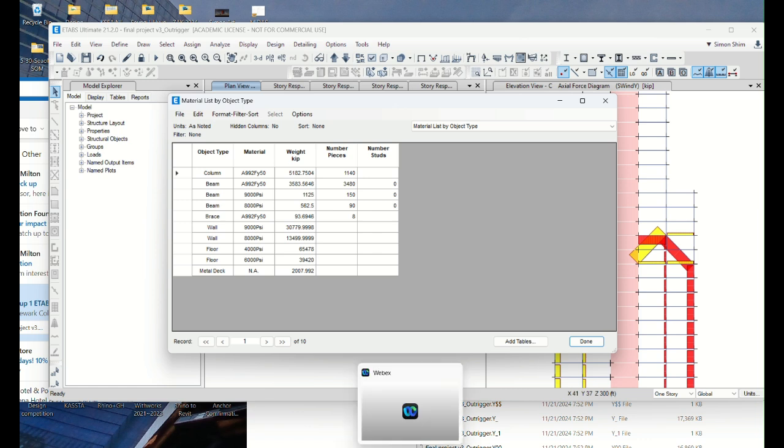But your model should have all the members. If you didn't include some miscellaneous beams, it's okay, and you can add that later based on a percentage. But generally this model has all the columns, beams, brace frames, filler beams, girders, and your number is very close to the real one. I would probably increase it maybe 3 to 5% later if I think some miscellaneous beams weren't included.